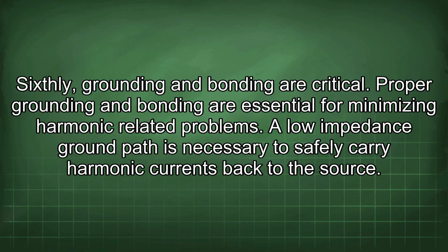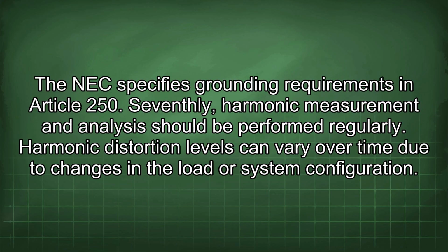Sixthly, grounding and bonding are critical. Proper grounding and bonding are essential for minimizing harmonic-related problems. A low-impedance ground path is necessary to safely carry harmonic currents back to the source. The NEC specifies grounding requirements in Article 250.